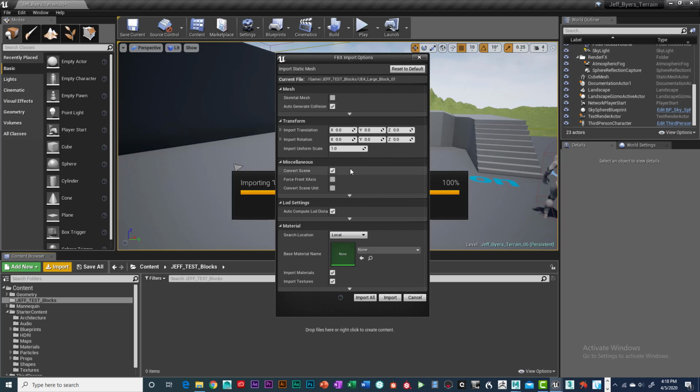So, another thing is, some of you have already figured out that you can do a collision that is per vertex in Unreal. How long do you think that's going to take before you bog down your graphics card and crash it? Not very long. Especially if you have a very complex object, it's going to take forever to try to figure that collision out. So do modular. Trust me, it's the way to go.